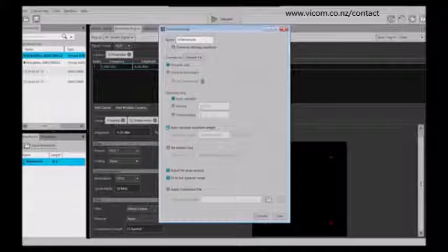So if you're creating a PRBS type waveform, it's going to calculate the length of the waveform to make sure that it fulfills that PRBS requirement that you've set. You can also set marker data such that when you create a waveform, you can have a marker at the symbol rate or for triggering or for other capabilities. So this gives you lots of flexibility on the markers.